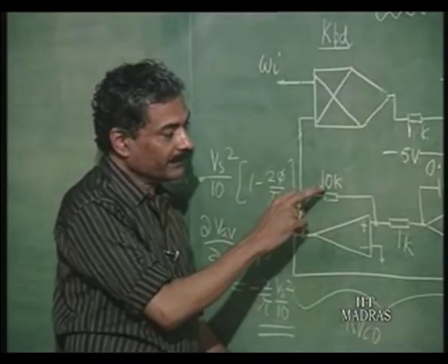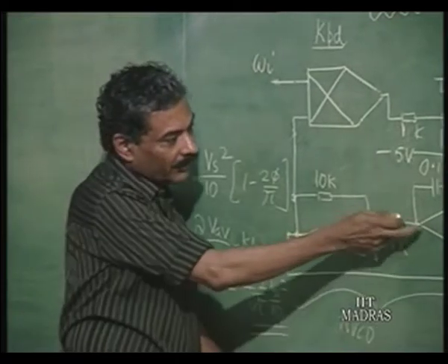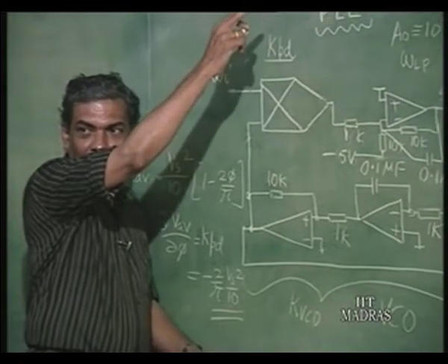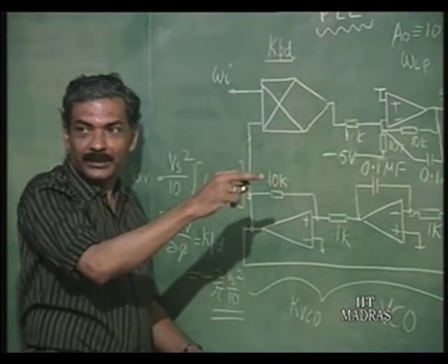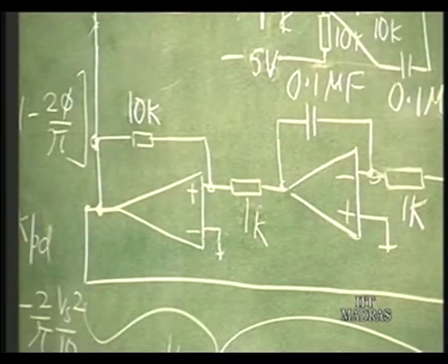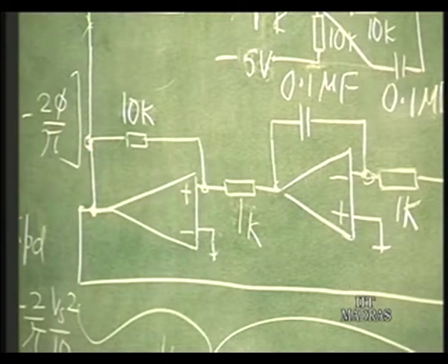Normally what happens is this is 10k and 10k, theoretically it should function all right, but this voltage is expected to go all the way up to plus Vs or minus Vs for change of state to occur, but it may not go because of the op amp limitation, right. So, this may not work with equal resistors in practice.